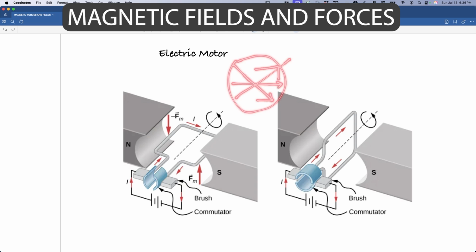Why is that necessary? Because when the coil rotates, at each and every point, two things happen. The length of the coil is always going to be perpendicular to the magnetic field, while the width of the coil is going to be parallel to the magnetic field. Got that? Now that's important because there would be no force acting on anything parallel. So no force on this side. At the same time, you have maximum force on this side and this side, right?